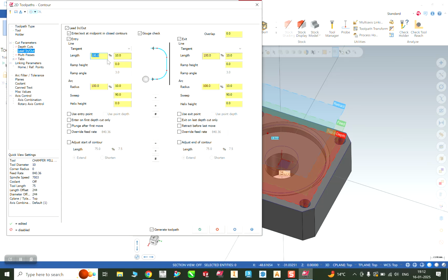And you will see that the tool diameter percentage also changes when we enter 60%. You can see here, the tool was 10 mm, and here also the radius needs to be 60%. You need to do that in any of the operations you perform. So for the exit also we are going to do that. We don't need to go there and change. Here below you will see this sign. You can import these values directly. Just click, and these will automatically change. Is it okay?